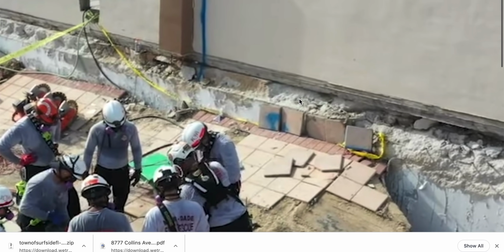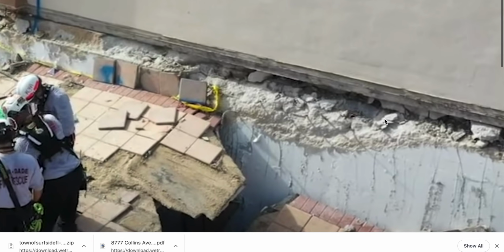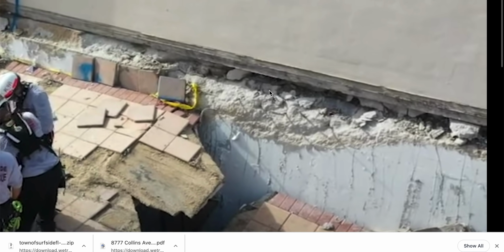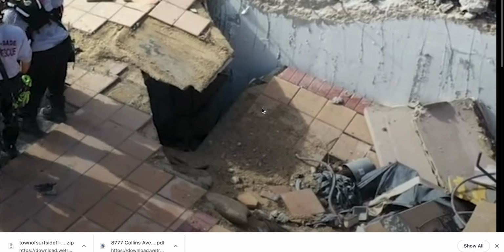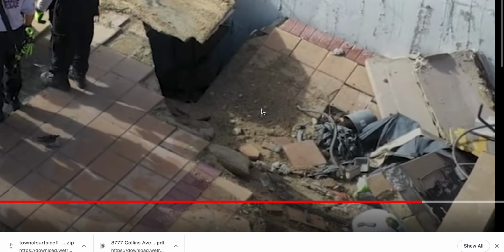This, on the other hand, indicates to me that the rebar pulled out all together, one section. So there might have been 3 pieces of rebar here, or 4, and all the way down to here. And they just pulled in one grouping. This grouping here, when it pulled out, it burst the rebar. There are cones, if you can imagine, that are the forces that are in play here when you're doing pull out. Yeah, this one I'm not sure if I meant that way, but you can go that way if you want to.